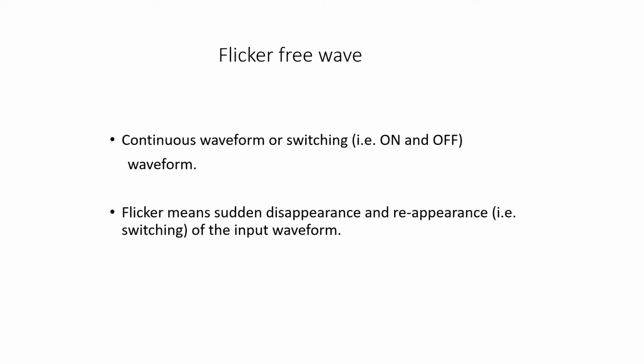This requires that the frequency of the vertical input signal must be equal to or an exact multiple of the sweep generator signal frequency. If the vertical input frequency is not exactly equal to or an exact multiple of the sawtooth frequency, the waveforms will not be synchronized. The display walks across the screen. That is, the pattern is not stationary. The waveforms on the CRO screen move from left to right or right to left when the frequency of sweep is not an integer multiple of the vertical signal.